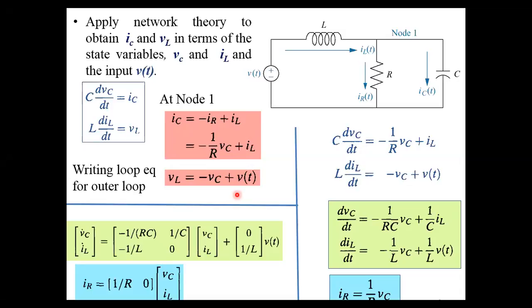For example, if a third order differential equation describes a system, then three simultaneous first order differential equations are required along with three state variables. From the perspective of the transfer function, the order of the differential equation is the order of the denominator of the transfer function after cancelling common factors in the numerator and denominator.